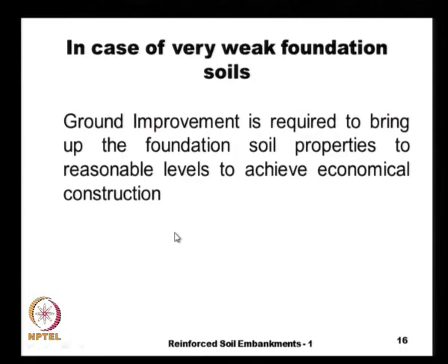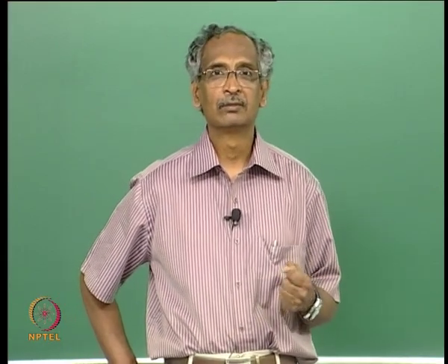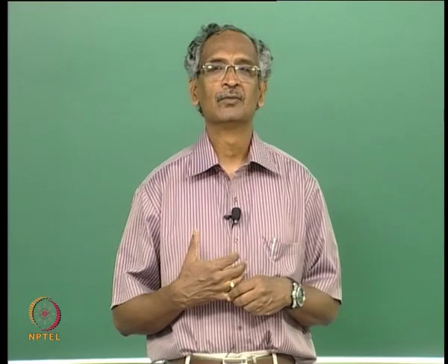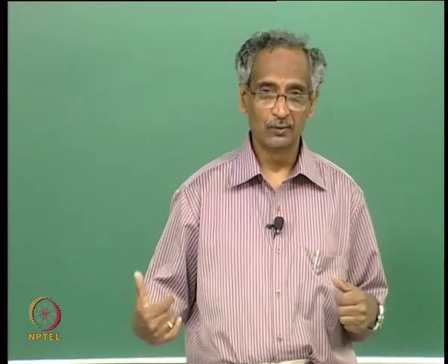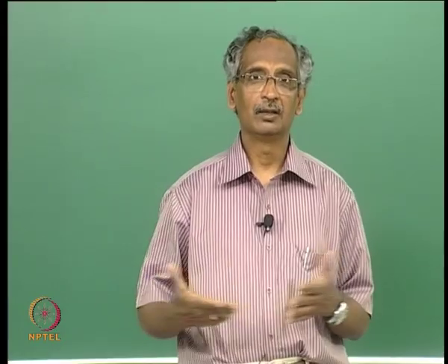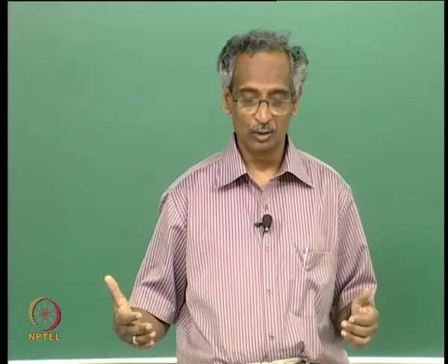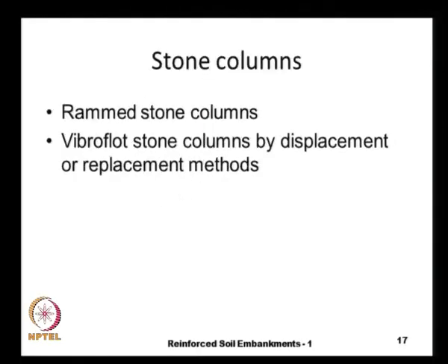Well, in the case of very weak foundation soils, we go in for ground improvement, so that we can improve the soil properties to some reasonable level wherein we can have economical solutions. Otherwise, the construction could be so expensive because of the requirement of a very large amount of reinforcement in the plane in the form of geogrids or geocells and so on. Some of these ground improvement methods, very briefly.